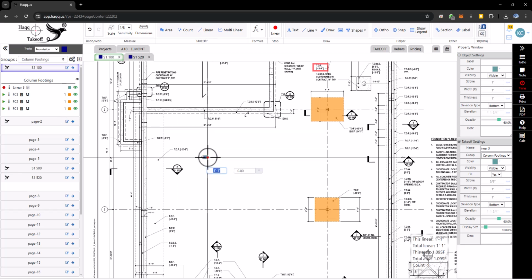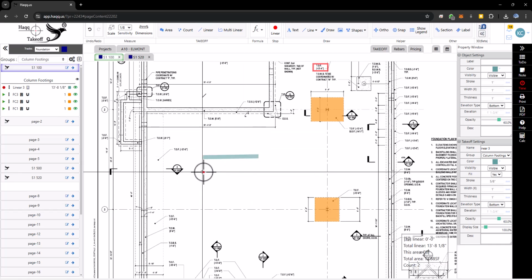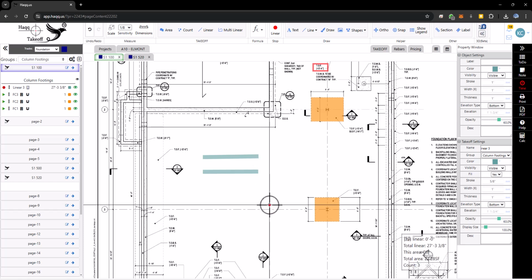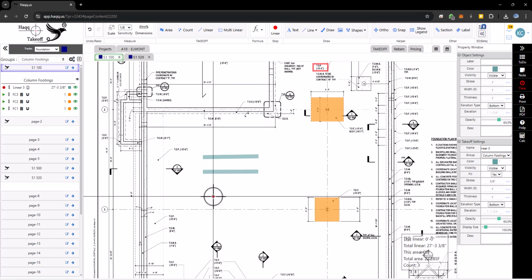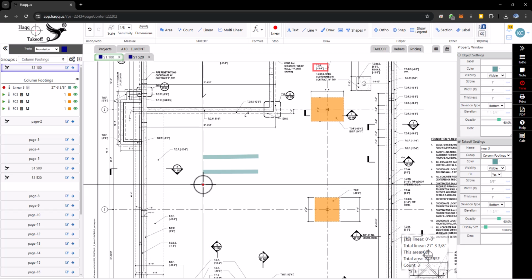After a second click, the first segment is finished, but the tool remains active, allowing you to continue creating new segments. Each new segment is completed after every second click. This setup is intended for creating individual segments rather than continuous lines. To end the element creation entirely, press the Escape button.